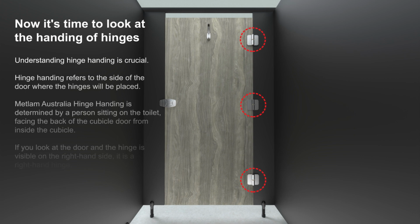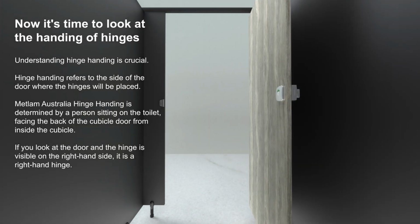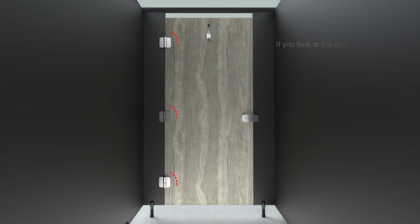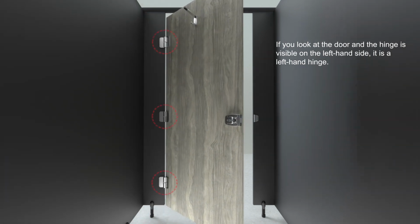Now it's time to look at the handing of hinges. Understanding hinge handing is crucial. Hinge handing refers to the side of the door where the hinges are placed. Metlam Australia hinge handing is determined by a person sitting on the toilet facing the back of the cubicle door from inside the cubicle. If you're looking at the door and the hinge is visible on the right-hand side, it's a right-hand hinge. If you're looking at the door and the hinge is visible on the left-hand side, it's a left-hand hinge.